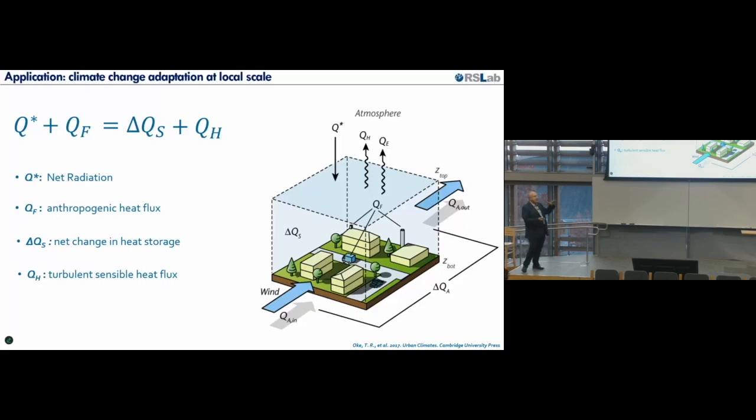So we have gradient of the temperature, we have the heat flux. So this is the mechanism that the temperature of the air is increased. And another part is used to evaporate water. This is the evapotranspiration, or the turbulent latent heat flux. So we use Earth observation to estimate each of these terms of the energy balance separately, as we can discuss